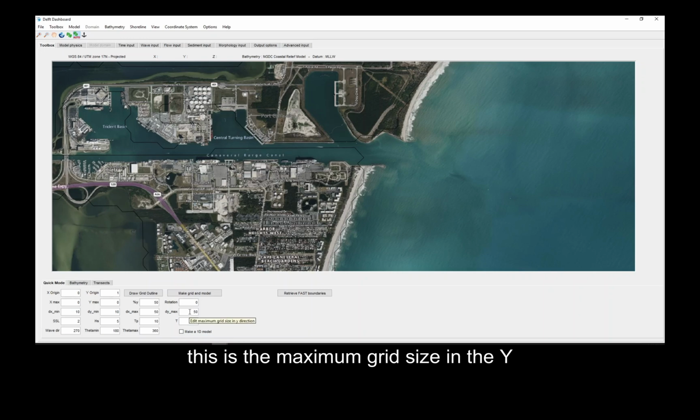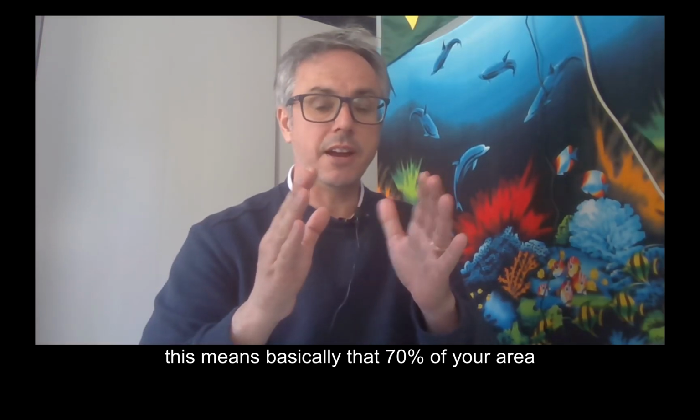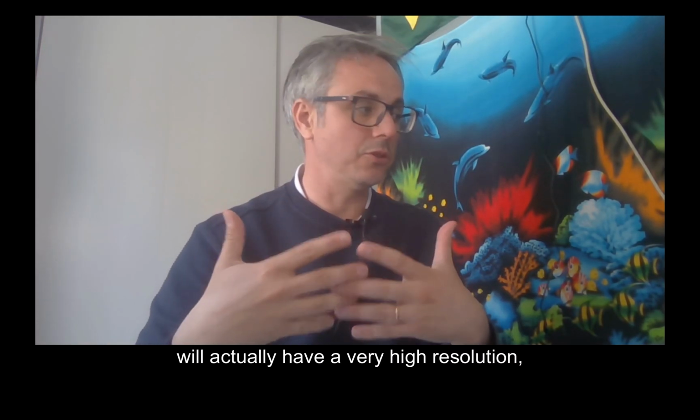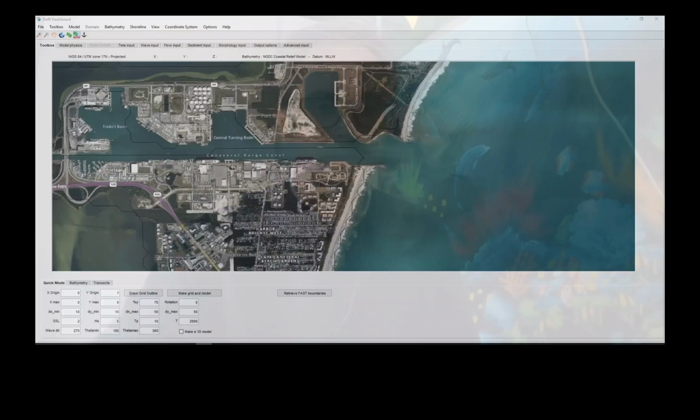So this is the maximum grid size in the y direction. So this is 50 meters, and 50 meters offshore in the x direction. The area we are interested in is about, let's say, 70%. So this means basically that 70% of your area that we will draw on the map will actually have very high resolution. So we'll actually have those 10 by 10 meters resolution. Okay.